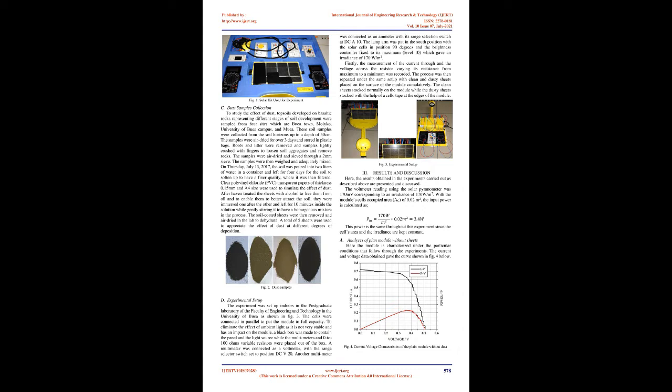For the experiment, a solar trainer was used, which is made up of a solar cell unit consisting of a standalone housing with integrated transformer and inclination-adjustable monocrystalline module containing 4 identical solar cells of 5 × 10 cm, off-load voltage approximately 0.5 V, short circuit current of approximately 1.5 A at 1,000 W/m².